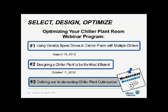So when your whole building is down to 80% load, I'd be at 80% flow on the condenser water pumps and 80% speed on my tower fan. The tower fan would remain there until I got to minimum condenser water rating. I can't go below on the chiller, be that 50 or 55, and then it would start slowing down again. So it slows down with load down to 80, and then once you hit 55, it slows down to whatever speed it's got to maintain that 55.